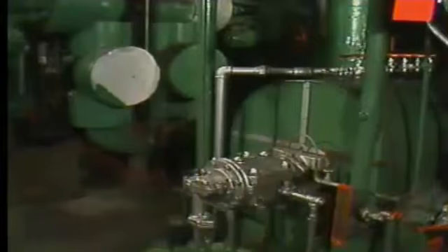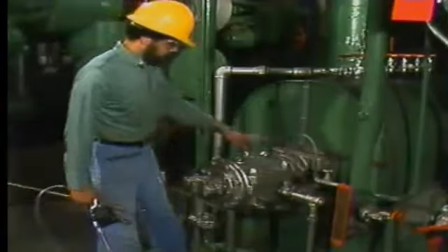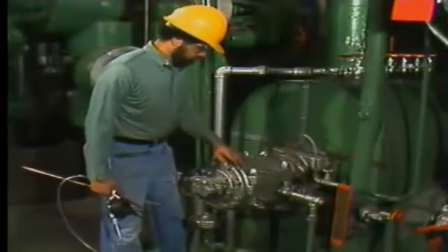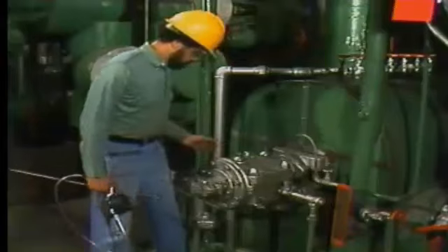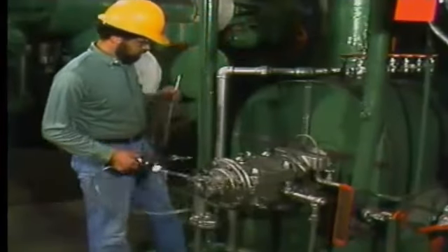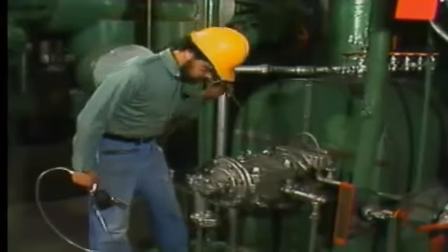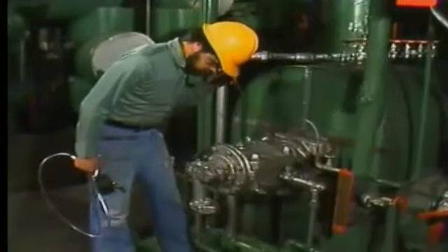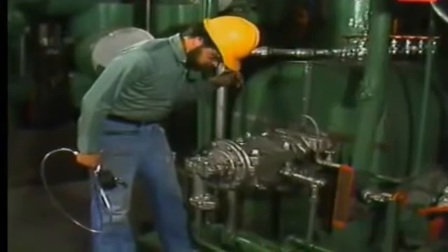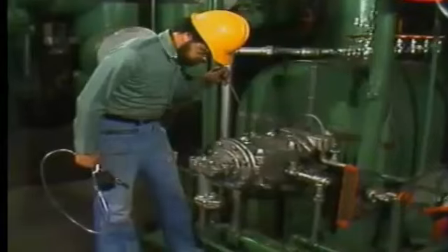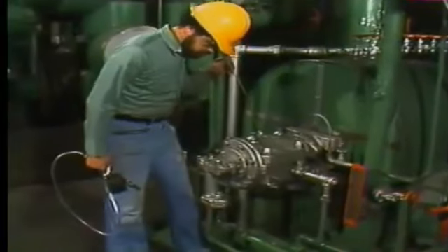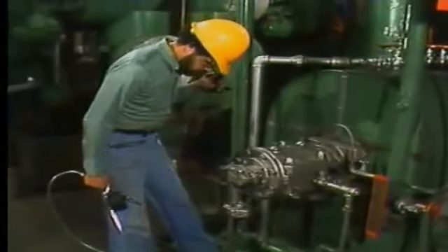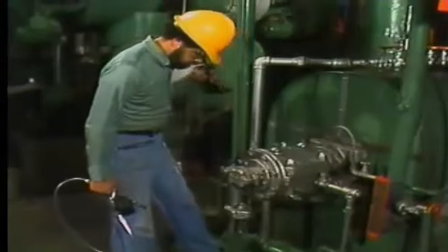Noise is another indicator of bearing performance. Excessive noise typically indicates a problem. A sounding rod can be used to listen to a bearing to see if there are any rumbling or grinding sounds while the shaft is rotating. An experienced mechanic can tell the difference between the normal operating noise of a bearing and the operating noise of a bearing that is beginning to fail.